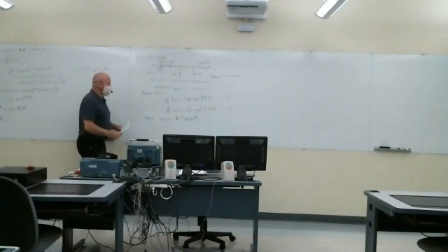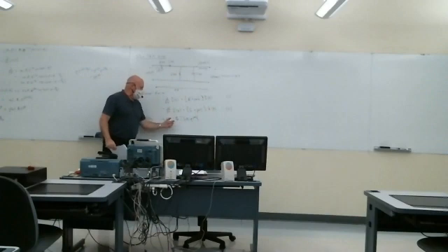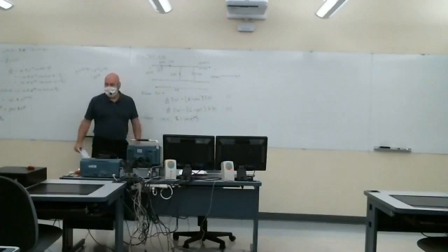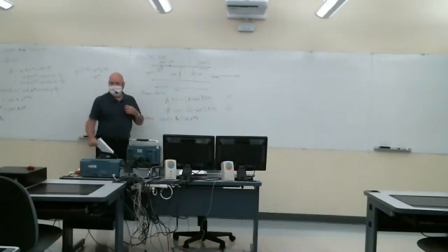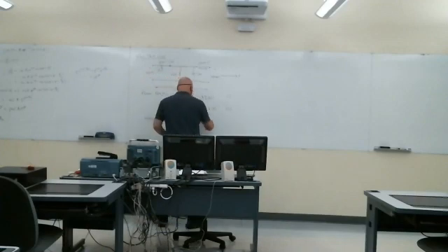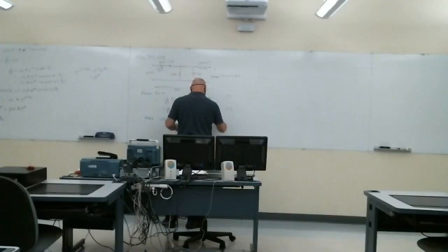Or equivalently, we can get the phasor from a time domain expression. Again, if this is a cosine, this is that complex number that involves the amplitude and the phase. But this is now a function of distance. And then similarly, I(z,t) is recovered the same way. It's our current phasor times e to the j omega t.